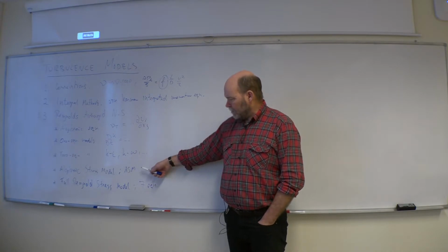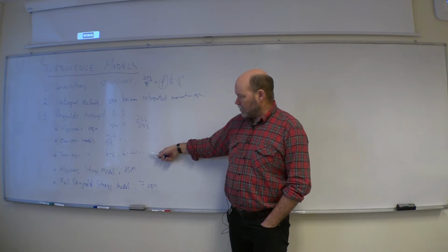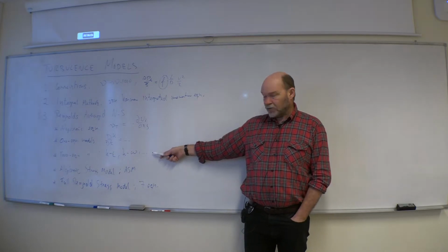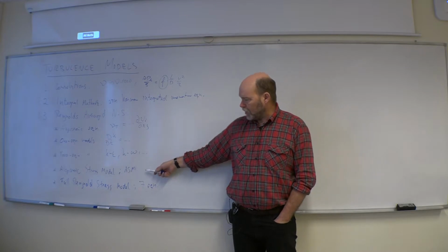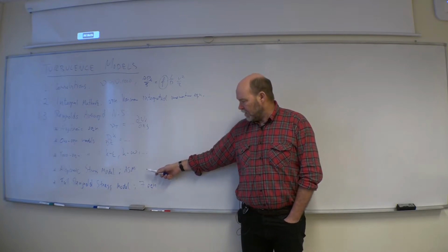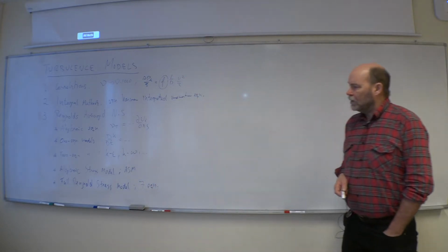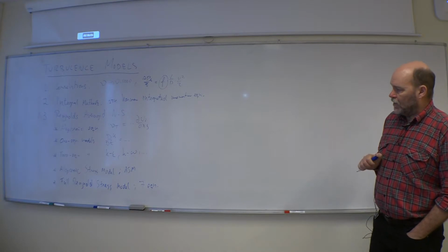The ASM is sort of an expansion of the two-equation level. So you take the solution from a two-equation model and then you play around only with algebraic equations to find the different Reynolds stresses. We'll come back to that one, how that one is made.